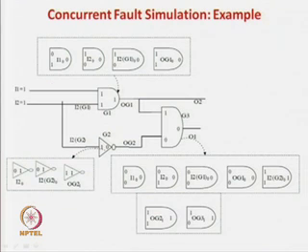Now, what we have in the normal case is 1 1 1 1 0. So, this is also 1 1 and this is a 0 and the answer here is a 0. Now, for this gate also there will be a lot of gates in the bubble which are actually affecting this one. So, now let us see how we can find out the number of faults affecting this one. You can see that this one depends on two values, the value here and the value here. So, this gate 1 0 is the normal case, and then we have to find out the bubble list for this gate, that is, what are the faults which are actually affecting this gate.